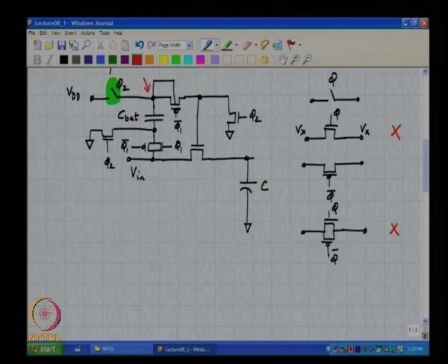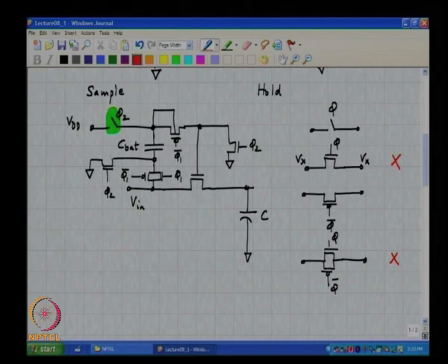In this case, however, clearly the potential of this node exceeds VDD. So, you cannot simply tie the body of the PMOS transistor to VDD, right. You need to tie it to the highest potential that the transistor is likely to see, and in this particular case that happens to be VDD plus Vn, and quite luckily in fact this potential always occurs at the same node on the left side. You understand? Okay. It turns out, as we will see going forward, that we will not be so lucky with the last switch, which is the one highlighted in green.